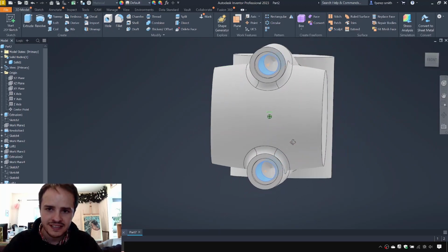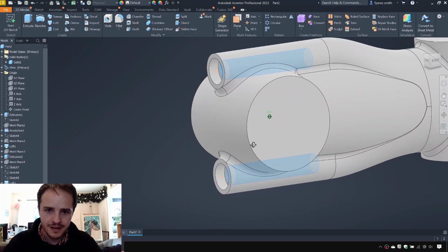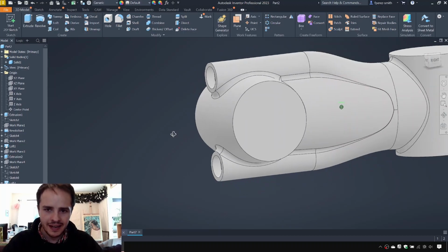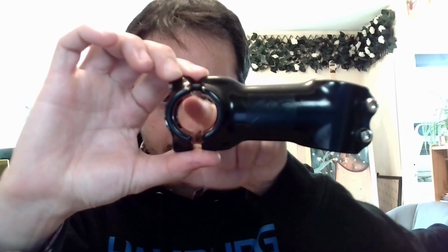You can't really see them in there, but that's there. And now what we're going to do is hide the work points. So right click, visibility, and we are going to cut that hole there and the gap that separates these two. And the reason why we're doing this will become apparent shortly. It has to do with adding in the thread. So we'll say that that's 28.5mm diameter.